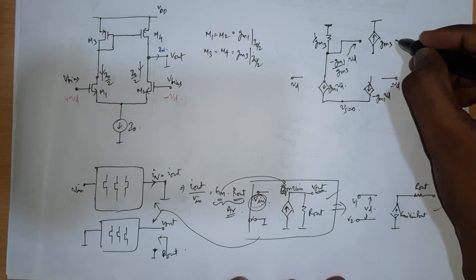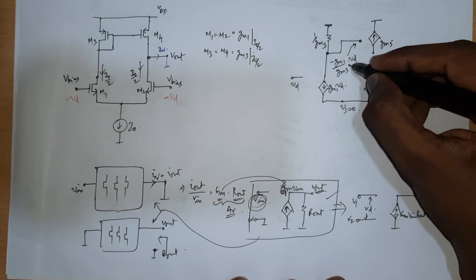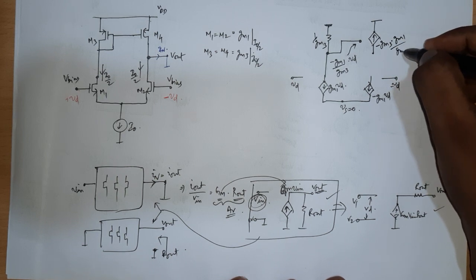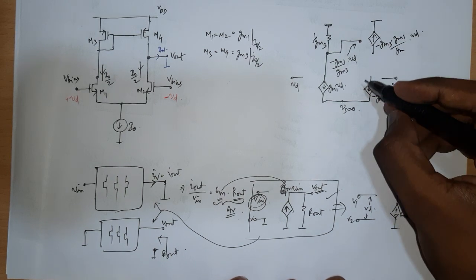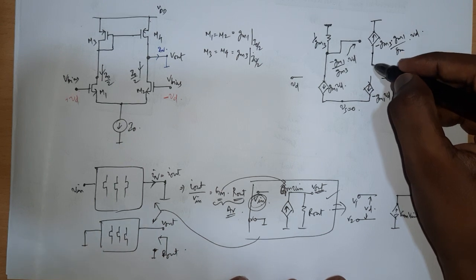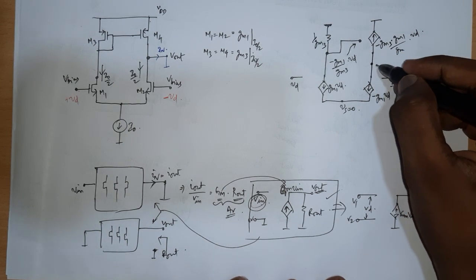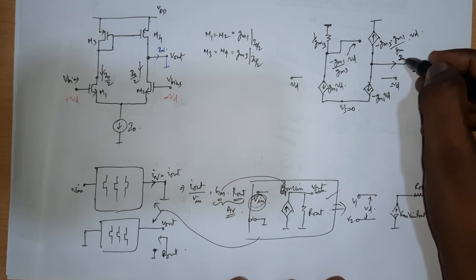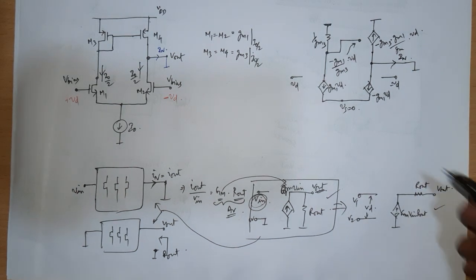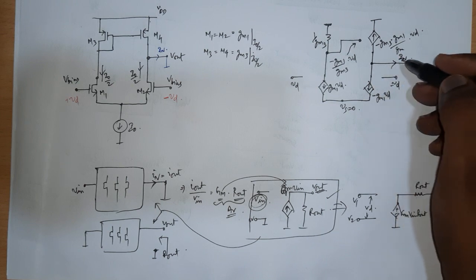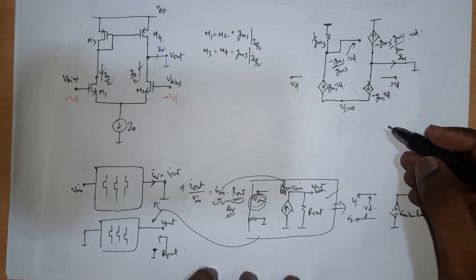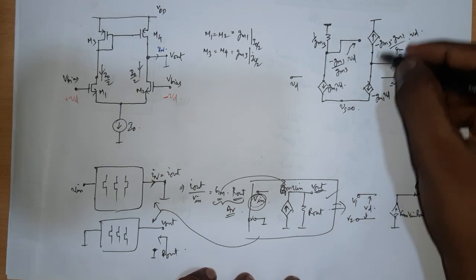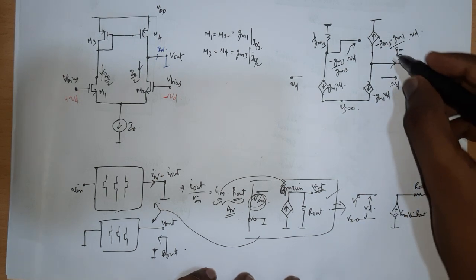and source is grounded, VG is this one, and GM is GM3 times minus this voltage, okay, minus GM1 by GM3 into VD, okay. This one and this one are grounded, connected, and here is where you have the output which is grounded again, and this current is a Norton current you want to figure out, okay. So you have three currents going out of this node, and you put the KCL at this node, you will get the answer, okay.